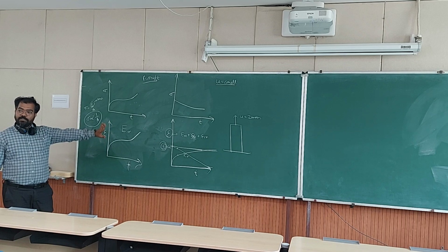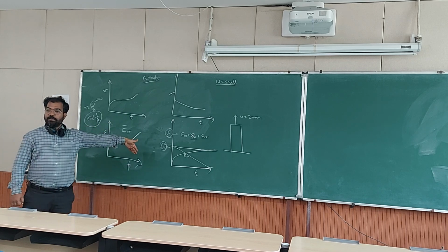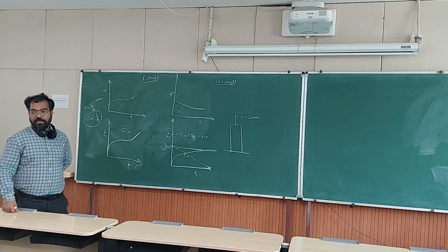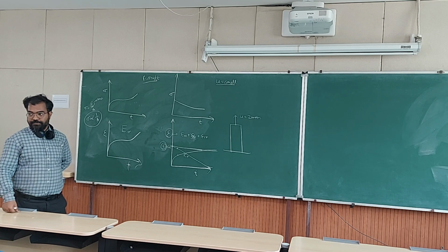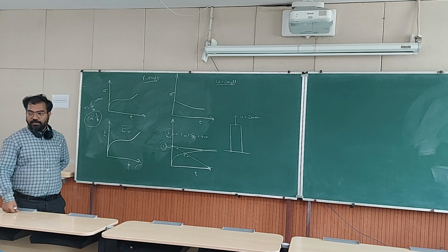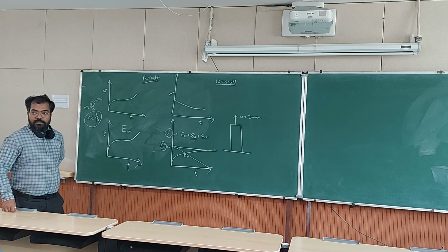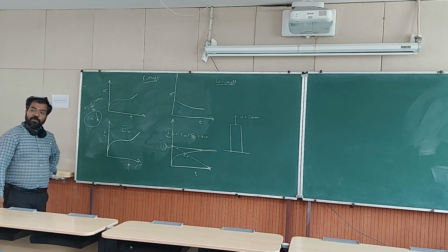And because these two are functions of time, you get the modulus time dependent. So elastic strain is not really time dependent, the modulus is changing. The stiffness of the material is changing. And these kinds of displacement control tests are also done in metals, but less in metals, more in polymers.